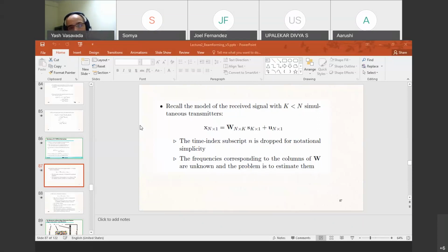We can do better. We can actually apply some windowing to the autocorrelation sequence before we take its Fourier transform. That windowing will allow us to trade off the width of the main lobe and the suppression of the side lobes. The rectangular window, which is the default window used in the DFT operation, has a specific size of the main lobe, and it has a specific suppression of the side lobe.